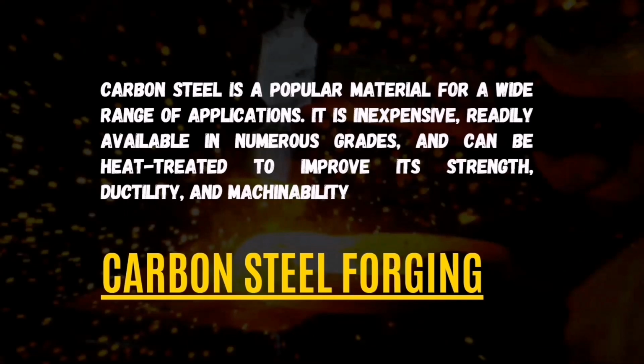So why is carbon steel considered one of the main common steels used in forging operations? It is because carbon increases the hardness and strength of a steel. As carbon content is increased, the steel becomes harder and stronger through the application of heat treatment. Carbon steel is a popular material for a wide range of applications. It is inexpensive, readily available in numerous grades, and can be heat treated to improve its strength, ductility, and machinability.